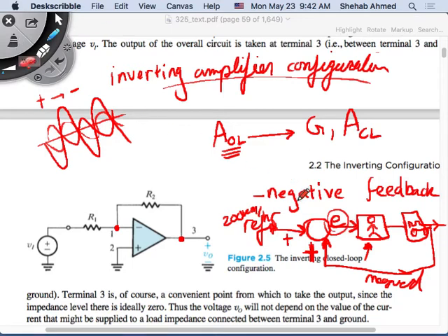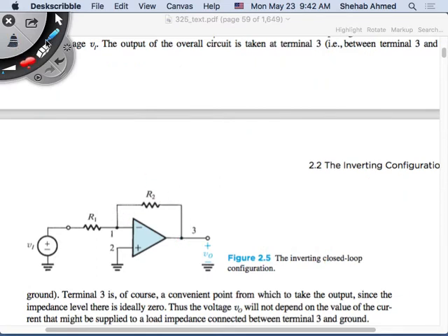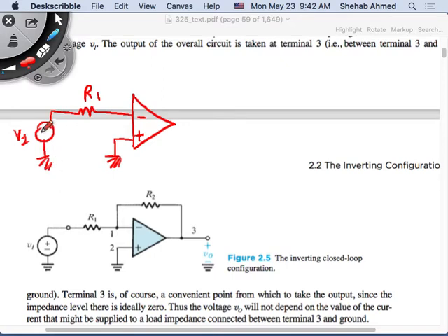Okay, negative feedback. So this is what we're utilizing here. So from a circuit's perspective, how does this negative feedback operate, and what's the consequence of having this negative feedback? So let's look at before adding negative feedback, right? What was happening? We had this op amp here, and let's say I ground this terminal for some reason. This is V2, I ground it, and this is V1, and I put R here. This is R1, and I put some VI here. This is open loop, right?